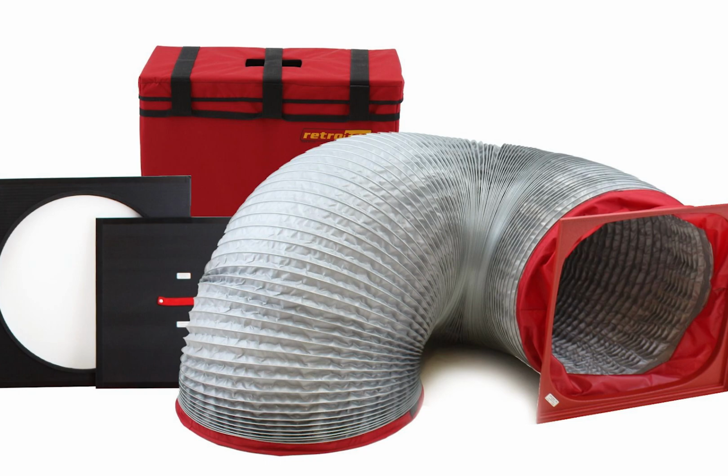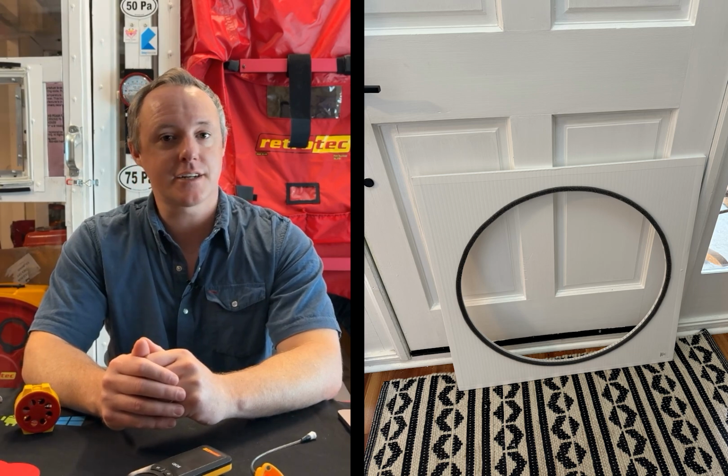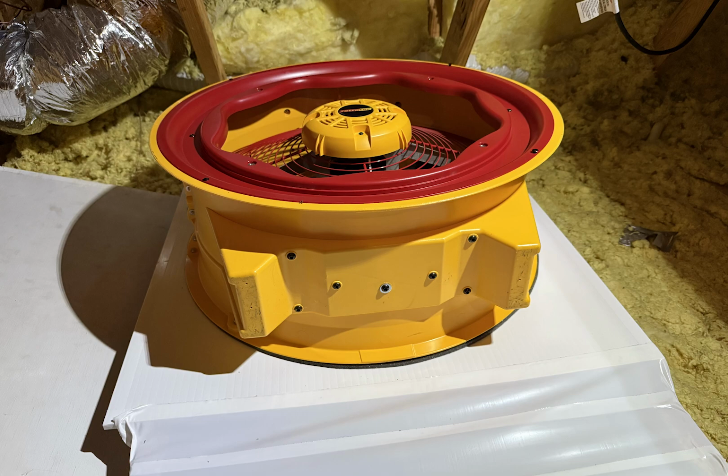It's called our leakage split kit, and it is a duct for the blower door fan that you can hook up to the attic. And it also comes with a corrugated plastic plate with a hole in it with weather stripping, so you can actually install the blower door fan horizontally and run it that way without a duct. So depending on the attic access, what you have room to do, you can install it either way.